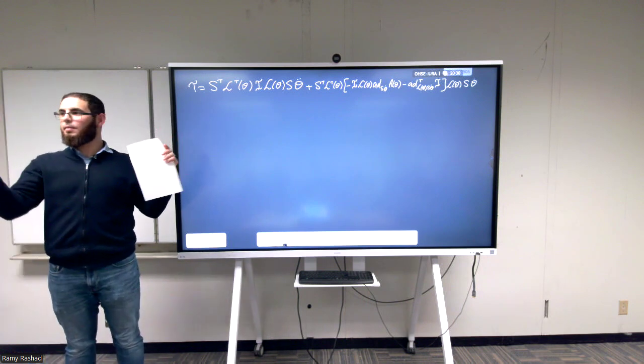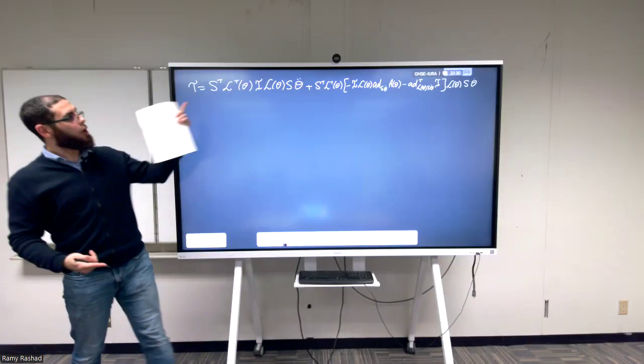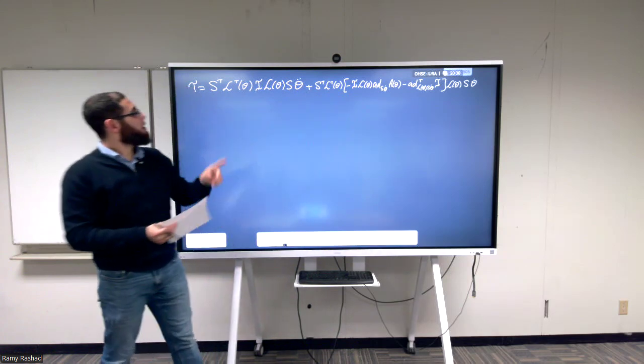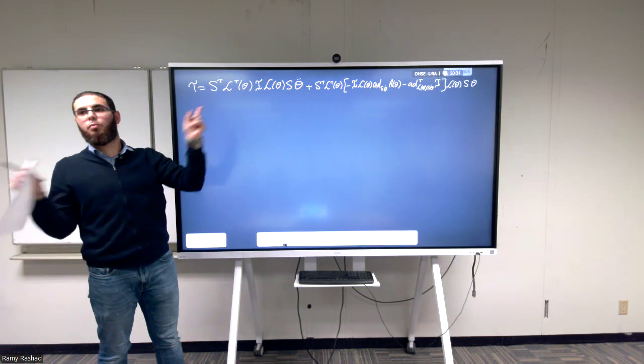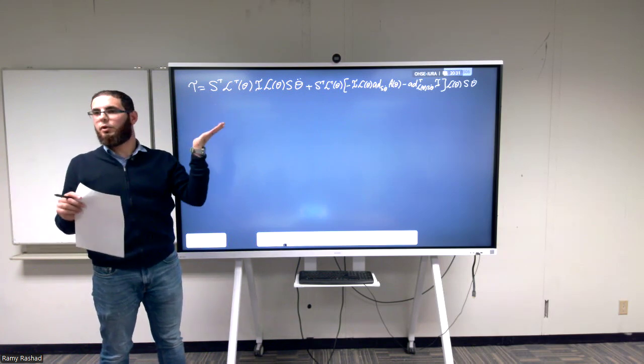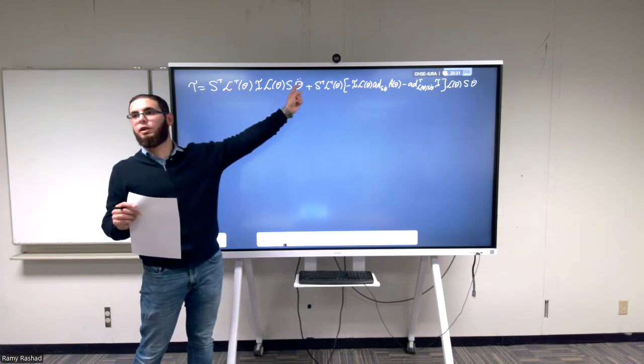When we had the 1D manipulator, which is the simple pendulum that we had, all of these terms were zero. And these 1, 2, 3, 4, 5 expressions were combined into one. We called it M, right? We just had M here. So this is the tau equal to M theta double dot that we had for the simple manipulator.